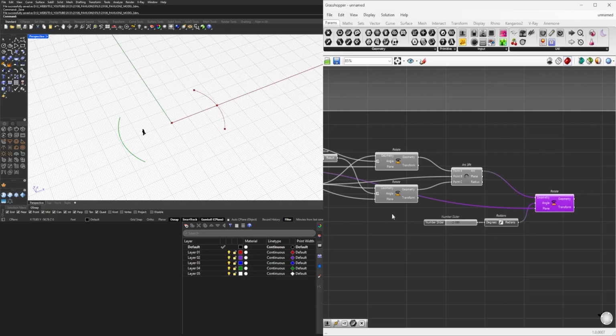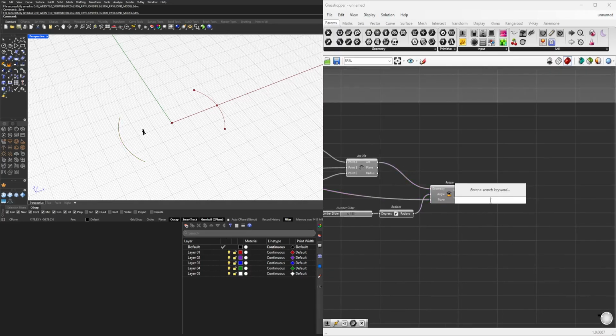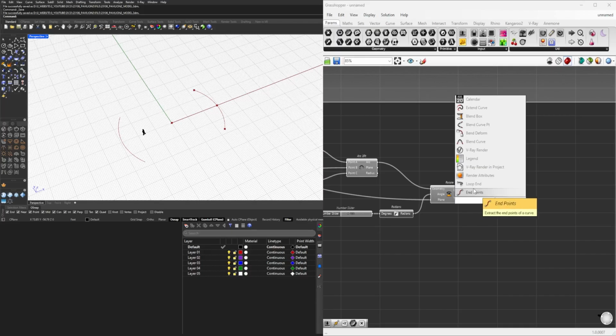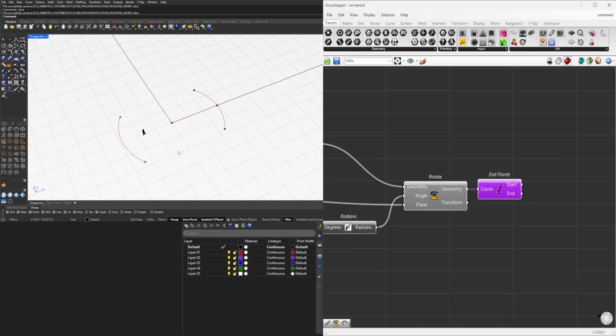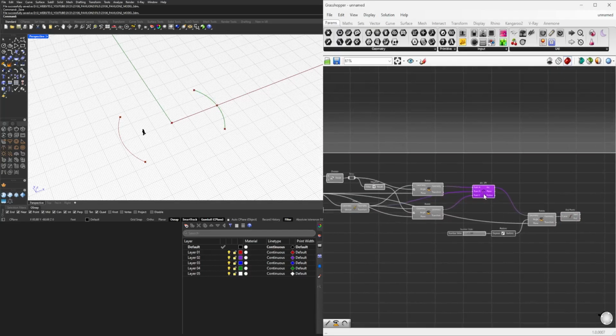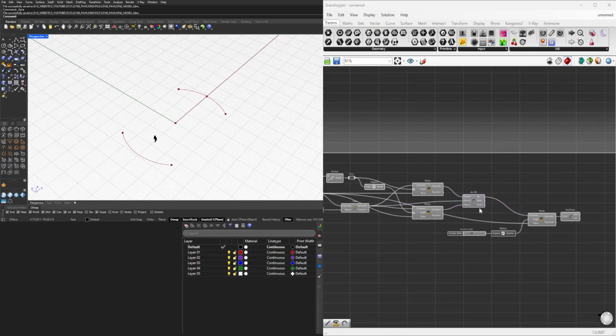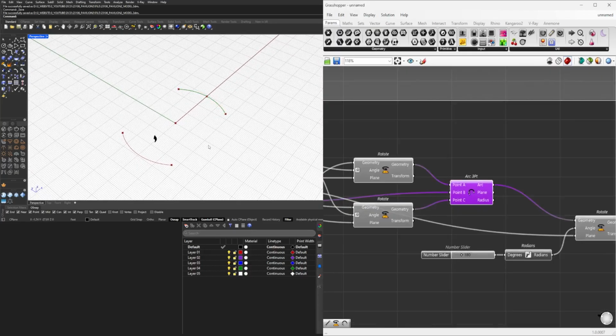that is left over. So what we're going to do is take this and bring in the endpoints. This will let us use these points and these points as the points to create the arc. So when we create a 3-point arc, we need the midpoint. So how would we get this point to this midpoint? Well, we can rotate it positive 90 and negative 90.